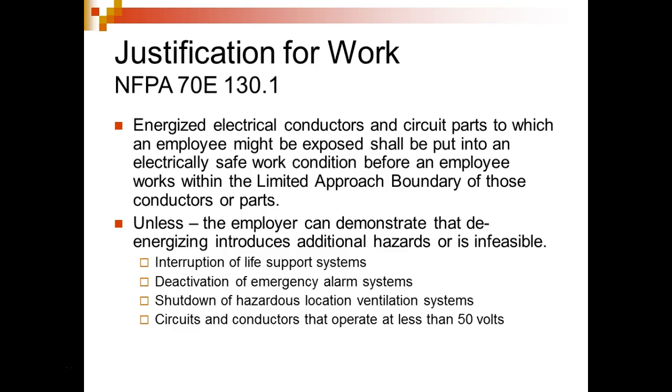Interruption of life support systems, that would be awful, right? So we've got life support systems. We're not going to de-energize those to work on, because if we do, we could do what? Kill people, yeah. A deactivation of emergency alarm systems. So we should never do that. Shutdown of hazardous locations ventilation systems. Circuits and conductors that operate at less than 50 volts.